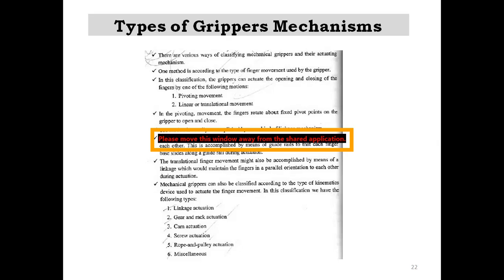Rotations make the grasping actions of the extender and the crank elements. So this cam and follower arrangement, which often uses a spring-loaded follower, can provide the opening and closing action of the gripper. The advantage of this arrangement is that the spring action can accommodate different size objects.